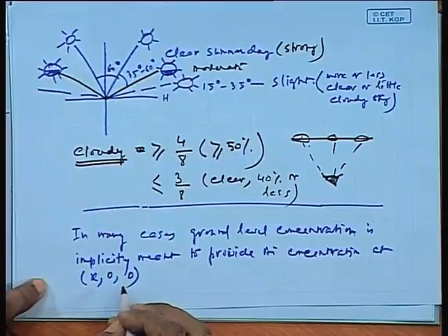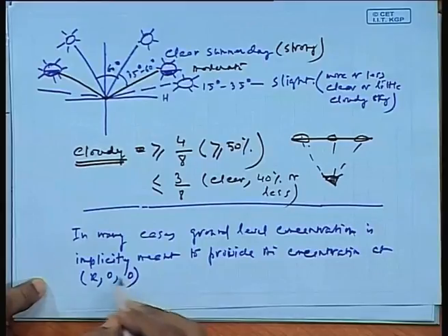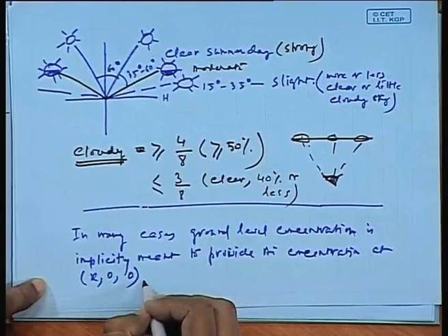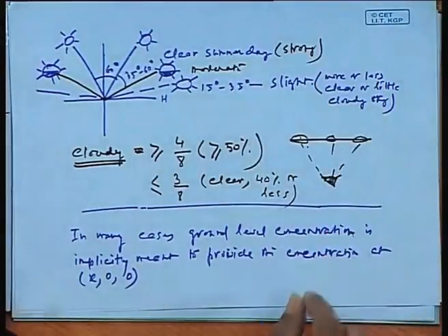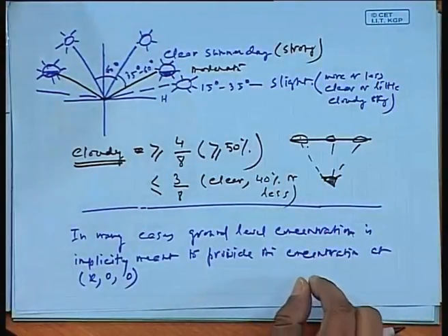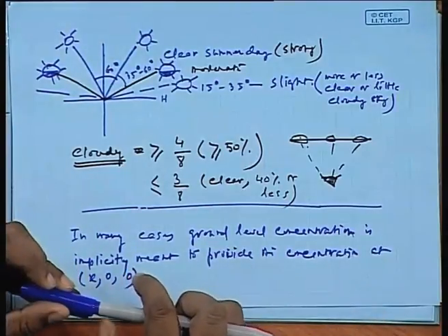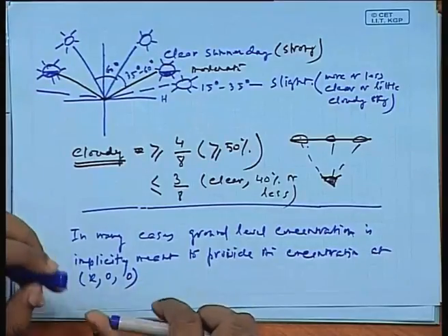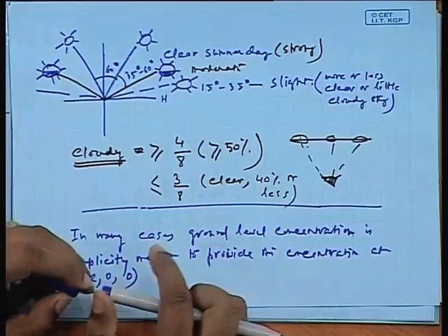It is on the center line. It is not y equal to 0, z equal to 0. So, the center line concentration, if you are going to find out, you can very well understand that in most of this Gaussian plume equation that I have said, one term reduces because of the exponential of minus y square divided by 2 sigma y square. You will observe that if y is put as 0, that particular expression reduces to 1.